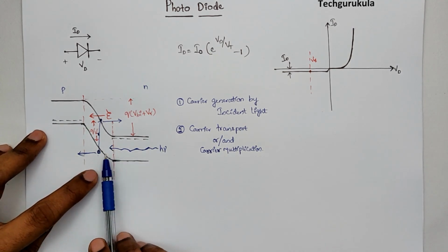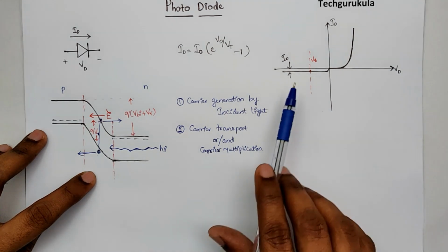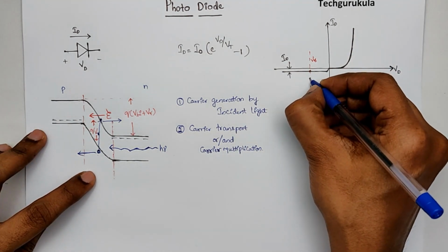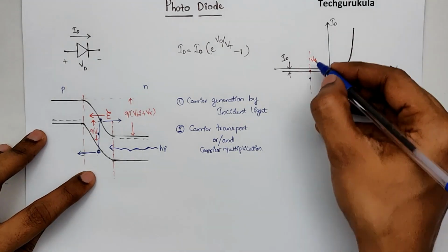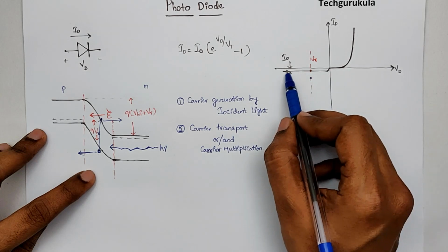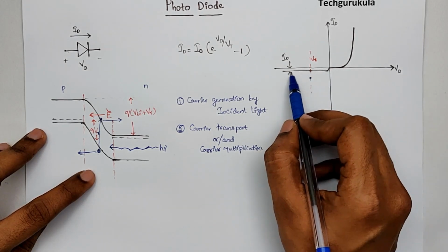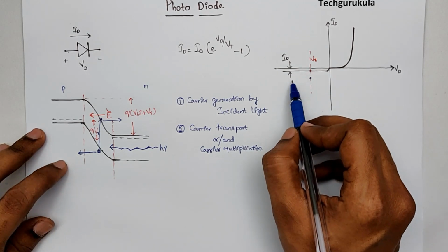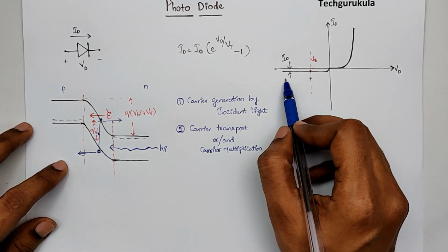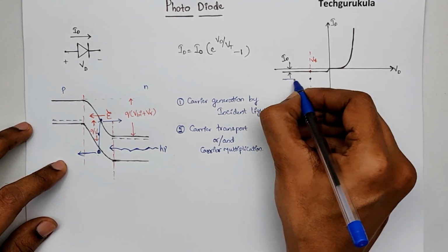As a result, the current that flows in reverse bias because of the incident light would be more, which means the current we would see is higher at this given voltage. The current in reverse bias is not really dependent on the potential that we apply, because the availability of carriers plays a bigger role than the applied potential. Hence, the current is constant.